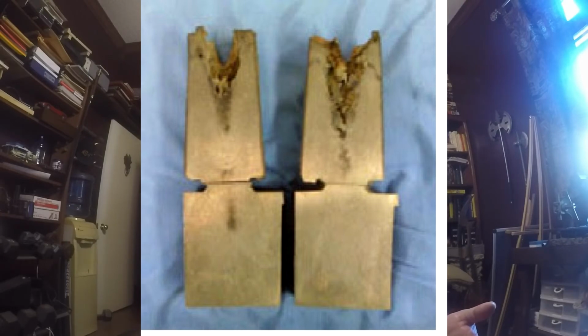And what looks like a line between the riser and the casting below might have been a parting line, because with the geometry of the blind riser, you wouldn't be able to wrap it and pull it straight up.